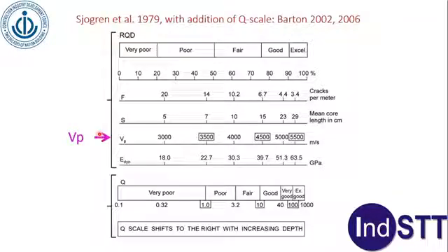If we are looking for conductivity of the strata to find out, for example, water zones, we go for electrical resistivity imaging. So here, instead of geophones, we are putting electrodes along the ground. We conduct the investigation. These days it's very fast. Imaging systems are available. And at the end of it, you have the resistivity distribution of the subsurface.